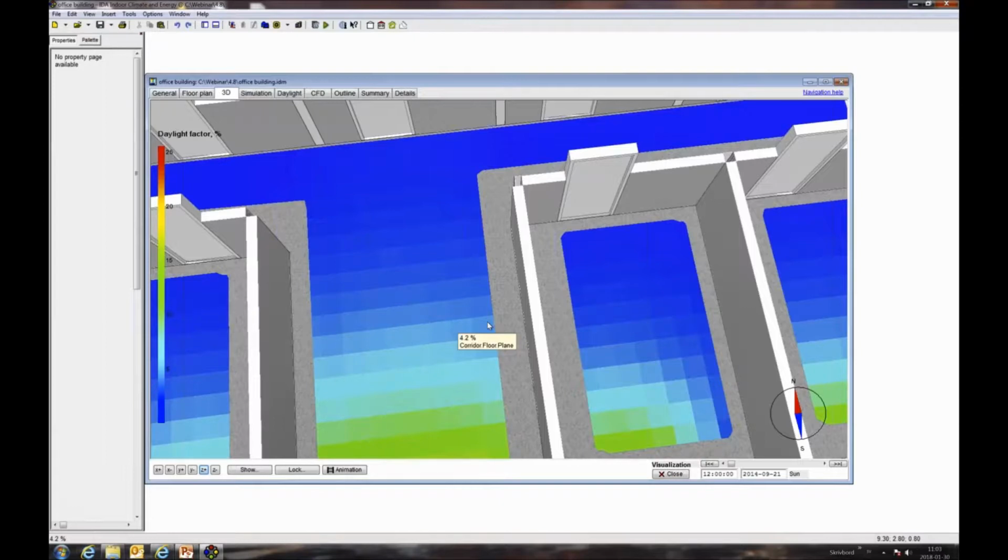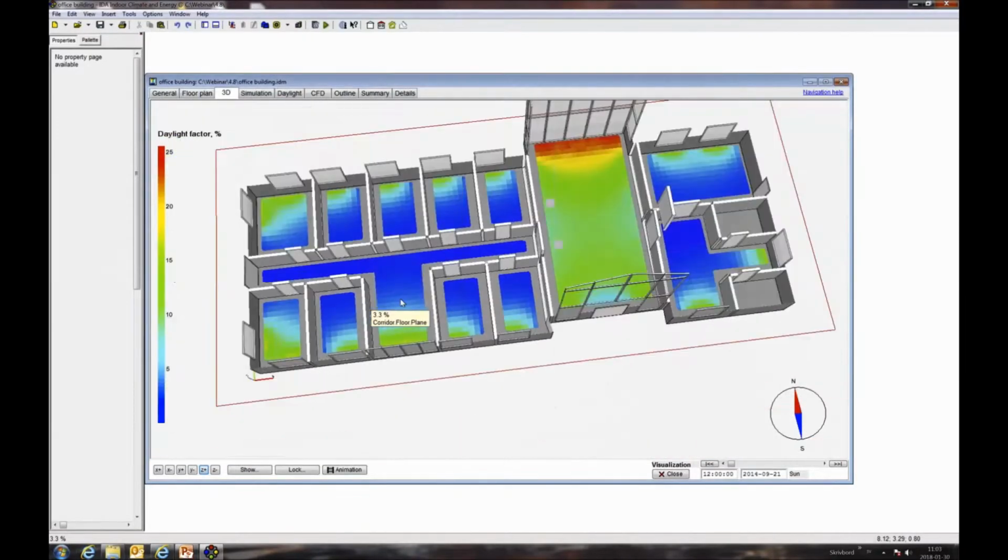Does room still have to be completely box-like for climate calculations? Yes, they still have to be shoebox rooms, and it's easier to add them now when we have this rotation in floor plan. Those of you who have attended sessions here during the years know that we are working on a new zone model, where you can do these detailed calculations, view factor calculations that they're called, with arbitrary geometry, but that will be for the next version of IDA ICE.